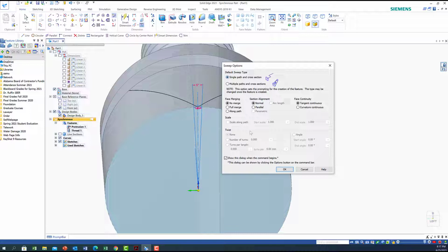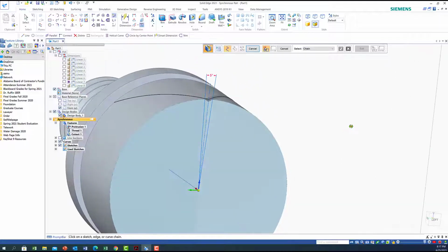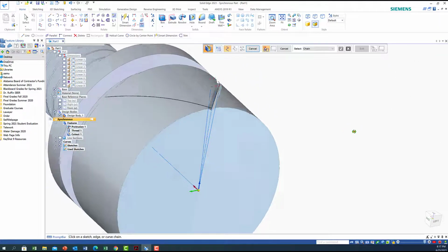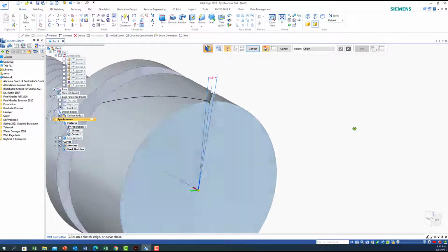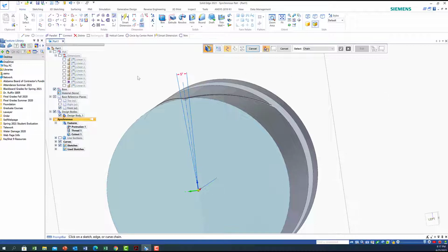And what we're going to do is, on the sweep cut out, I'm going to click on the line here, and I want to say okay. Now I need to get the shape here. Yes, this shape, and say finish. So what happened is, as you can see here, we did a cut here. You see this groove here? Yeah, okay. See, we did this groove. Okay, now don't forget that we need to get locked to this area here, so just fine.